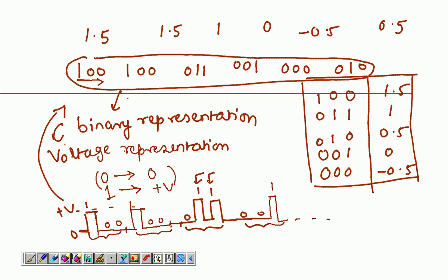So a binary word in this case consists of 3 symbols because we need to show 5 different voltage levels. Up to 8 levels, we can just use 3 symbols. Now, this is where the problem comes. Let's say when the signal transmits through the channel, you definitely have a lot of noise sources, you have noise imposed on the signal. So how do you remove the noise?